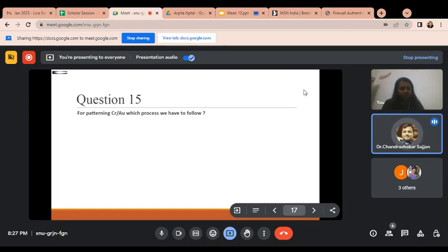Yes, we'll go for soft baking. I think we will place it at 90 degrees Celsius for 1 minute. Yes. Then after that, the bright field mask.